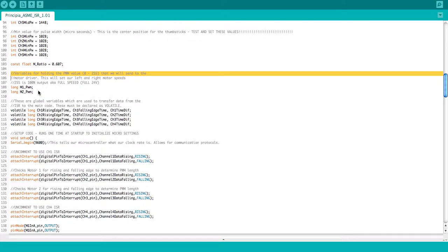And if you've not really read much about PWM or have much experience with it, it's not terribly complicated, but just think of a bunch of pulses that have an amplitude of, say, 5 volts, and if it is high for 50% of the time and low for 50% of the time, so 5 volts for 50% of the time, 0 volts for 50% of the time, the average value will be 2.5 volts, which will effectively change the motor speed. Big benefit to PWM is you actually are applying the full voltage, the full 24 volts, or in my little explanation, 5 volts, which allows you to have more start and stall torque on the motor.